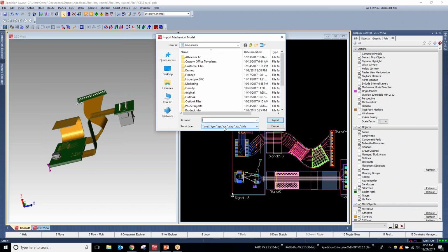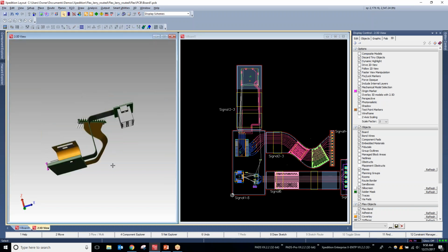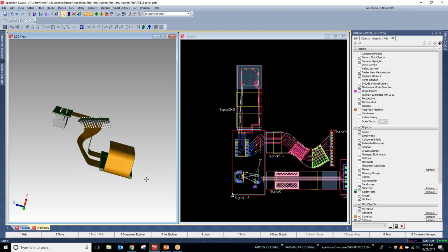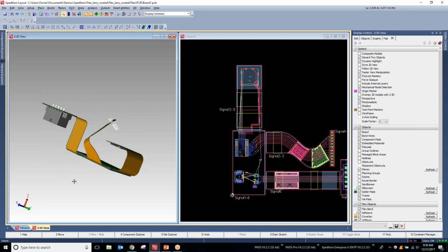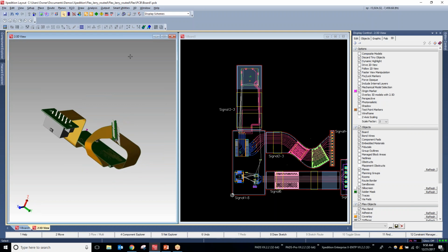So what you can do is bring in your enclosure and then fold this all up exactly like how it's going to be in the real world, after you've created the design, just to make sure that everything is going to fit from a component perspective, from height, as well as fitting inside that enclosure with enough bend room so nothing's making too many collisions. Okay.